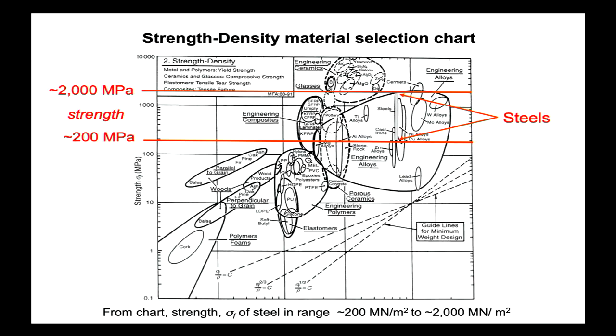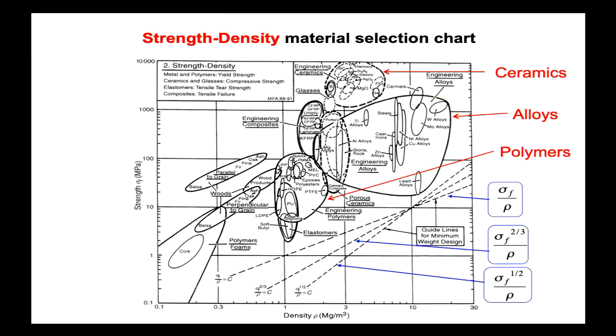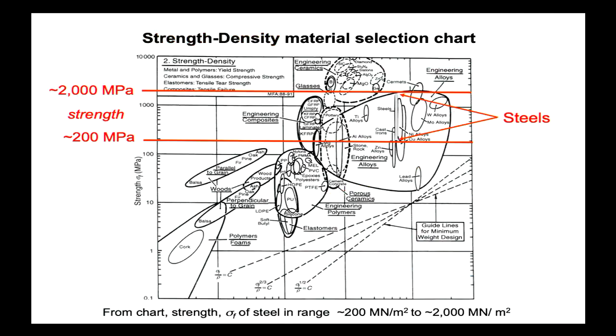Now, in this case, we've got density of steel being a very thin variation across density, but a very wide variation from about 200 megapascals to about 2,000 megapascals. So mild steel, and you can imagine high strength, probably getting into brittle, spring-like materials. Yield strength is probably very close to ultimate tensile, all those kinds of things going on.